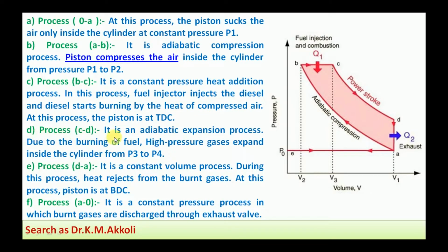Then the process C to D. Okay, the process C to D is the expansion or power stroke. It is an adiabatic expansion process. Due to the burning of fuel, high pressure gases expand inside the cylinder from P3 to P4.